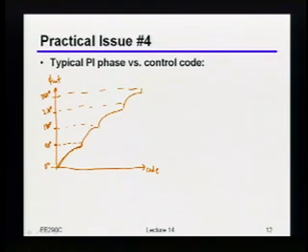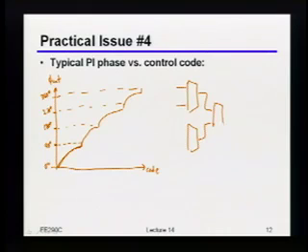And by the way, I'll just give you a hint. Pretty common way for you to build that mux would be something like this, with 2 stages. Okay, so there might be 0 degrees here. Let's say there's 90 degrees there, or let's actually just make it 180, and let's make that 270. Okay, and then this is your final clock at the output. And obviously there are 2 sets of control bits here. So now, why is it that changing that... By the way, obviously when you change the quadrants, that's directly associated with changing the mux codes.